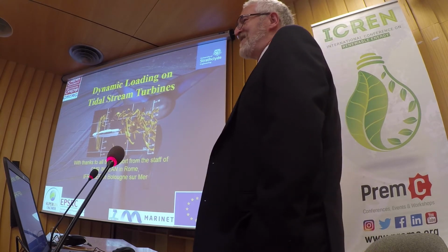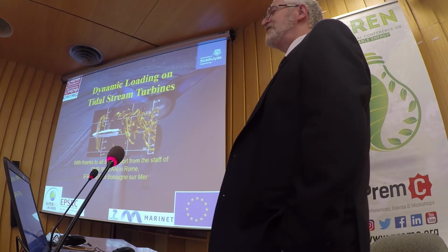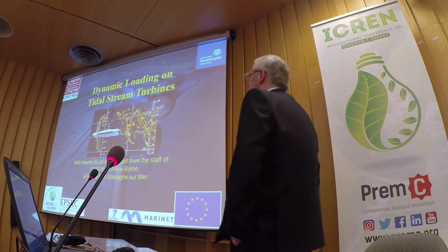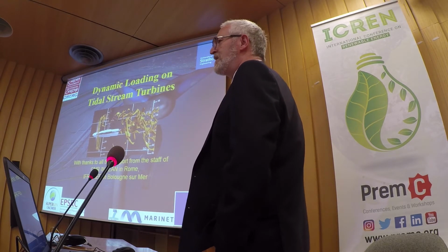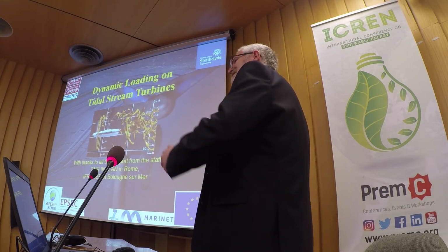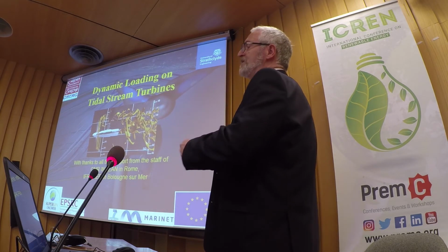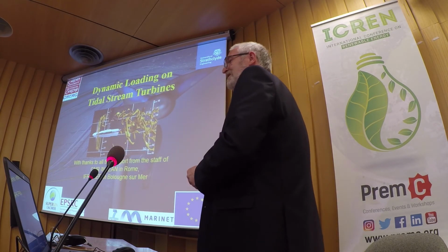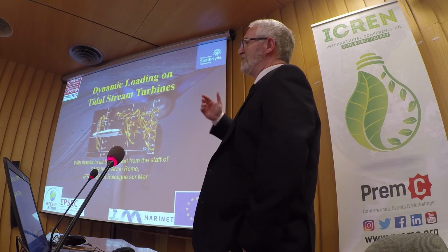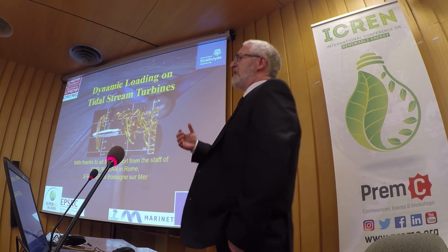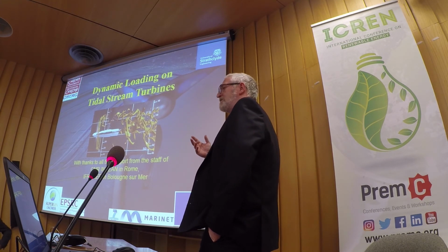Seriously, why do you have to have the second turbine torque controlled? You don't. We've done speed and torque control. Why was it done? Basically, the ones that are deployed are generally operating on a torque control. On the laboratory scale, we would traditionally operate them as speed control. The reason for it is you get clean characteristic curves, and then the errors that are involved are down to the instrumentation you're measuring on. Whereas we've now shown that with torque control, so mimicking full scale, you are actually getting some higher loads and torques as a result.